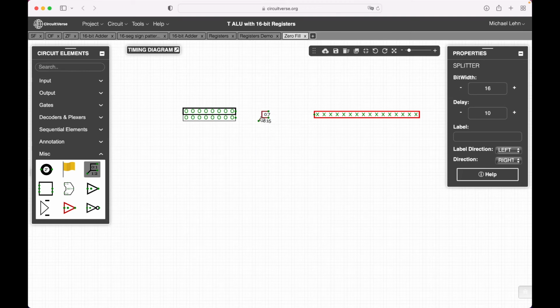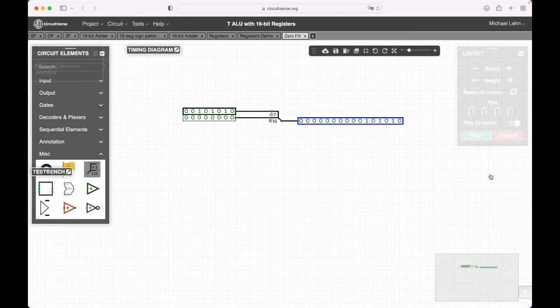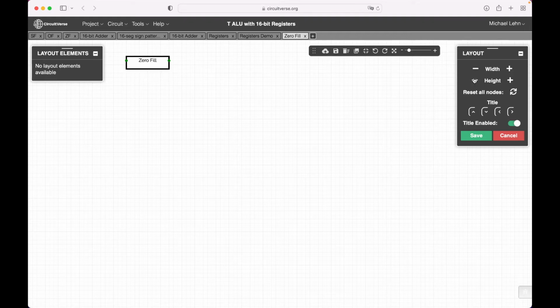like that. So I just changed the orientation or the direction, and now I combine the bit pattern that is given as the least significant bits with the zero extension as the most significant bits, and this becomes the generated output, the generated zero extended 16 bits. Now, because we want to use this later, make sure that this layout is nice so that we have a slim and slick building block.